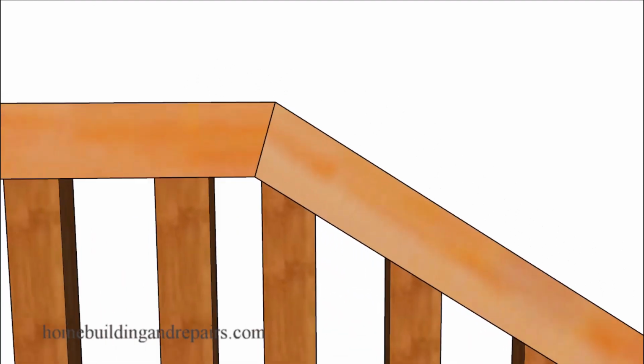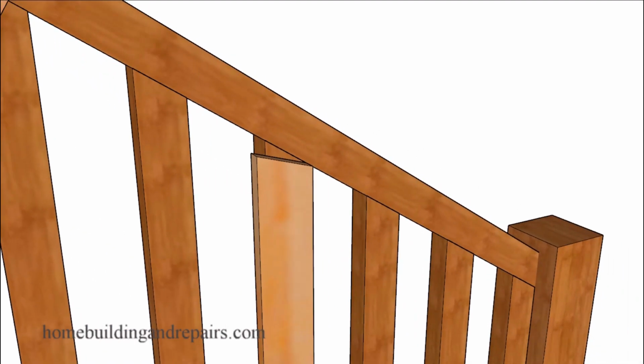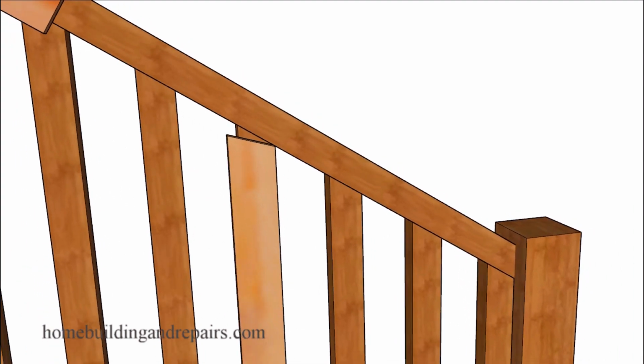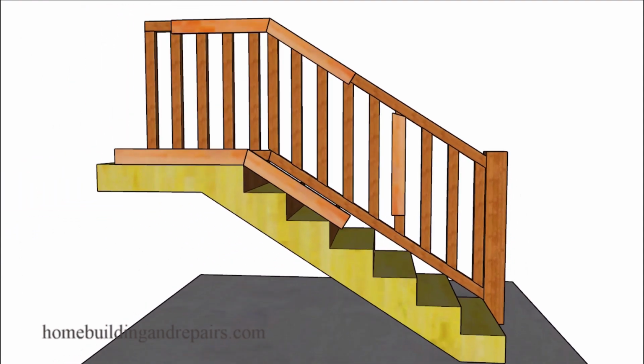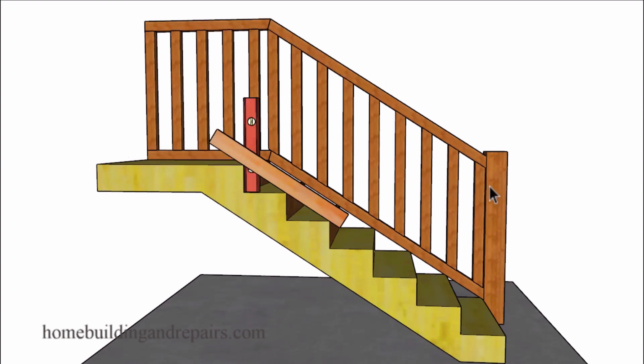And since these are pretty much the only two angles you're going to need to build a guardrail or a handrail like this one here, or most guardrails and hand railing miter cuts where they join something like this or something like this, then this project just got a whole lot easier. And to figure out this angle here and the angle for our balusters, we're simply going to grab another piece of wood, set it on top of the stairway, and then use a level or a straight edge.